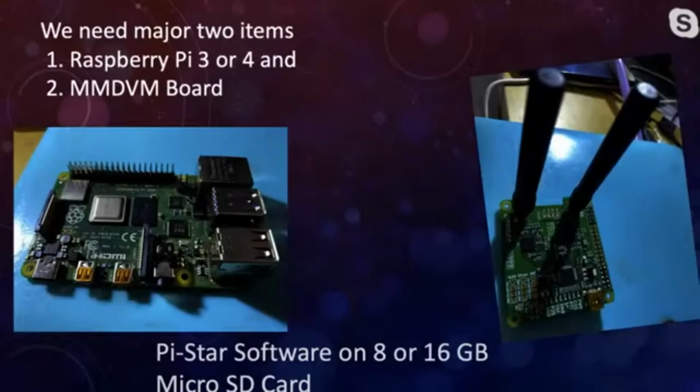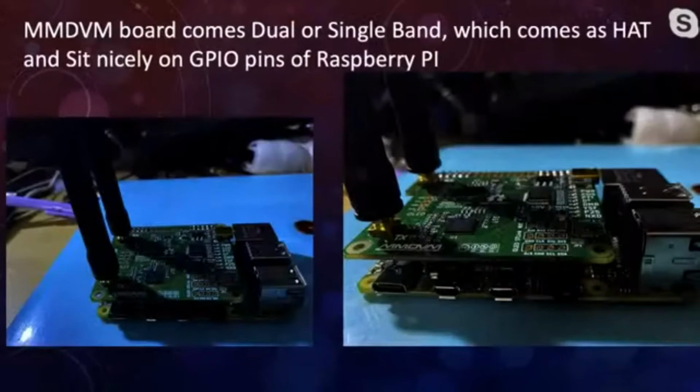Then you have an MMDVM board, which is on the right hand side. It comes as single mode and dual mode, also VHF, UHF mode. So both you can buy, or one board with one for transmission, one for receive; that type of mode is also available. Pi-Star software goes on an 8 or 16 GB micro SD card. You can go 8 also, 16 also. It is enough for running the software and keeping the database. The MMDVM board comes dual or single band, which comes as a hat and sits nicely on the GPIO pins of the Raspberry Pi. So this is the Raspberry Pi sitting tightly, in the close shot I have shown you here.